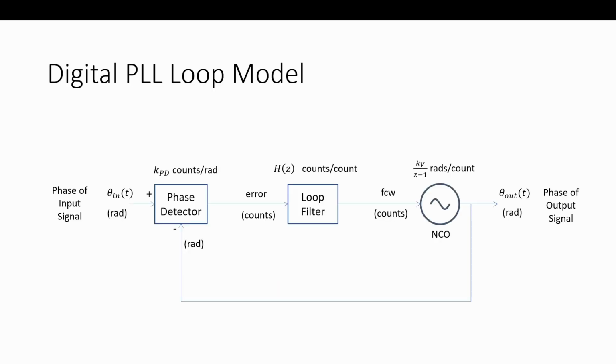And the digital loop model, same thing we did before, except what you're seeing here, like we put the S in the denominator before. Remember I said the origin on the S plane is Z equals 1, the Z plane. So that has a pole at Z equals 1. That denominator goes to 0, the pole is at 1. So 1 over S, the integrator in Laplace, has a pole at S equals 0. The pole is right at the origin. So you map it over to Z, right at Z equals 1. So that's doing the same thing you saw before.